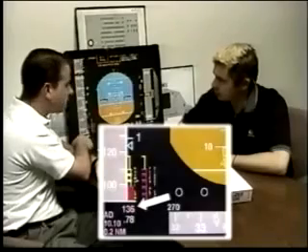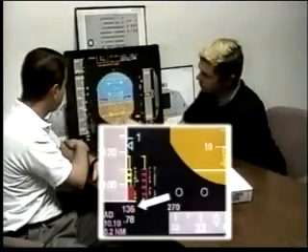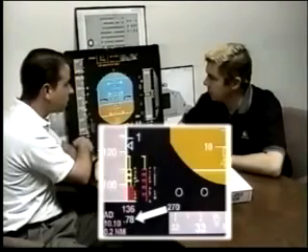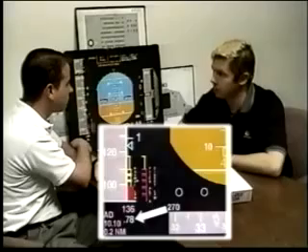I see a magenta 136. What is that? That's a managed speed off scale. It's basically the same as this. These two are similar except this is off scale low. We could also see it up here, off scale high. Okay. And below it is a green .78. And that's the Mach indication, and that's present only when we're Mach 0.5 or greater.